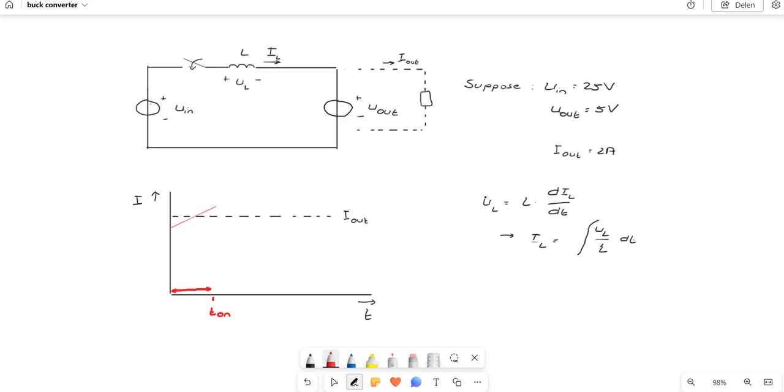So IL is suddenly changed by means of a step by opening that switch. So the derivative of IL is very high, and we get a very huge voltage over here, which leads to a spark across that MOSFET, which will often destroy it.